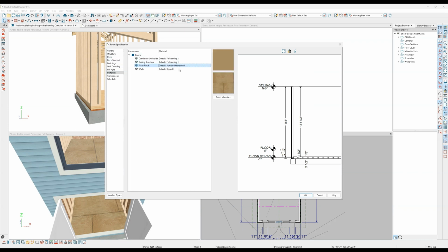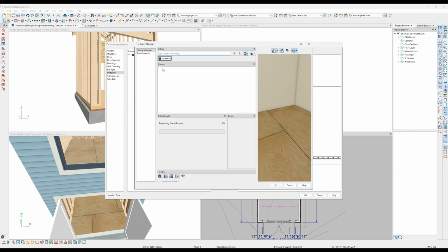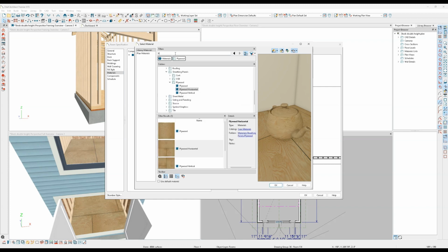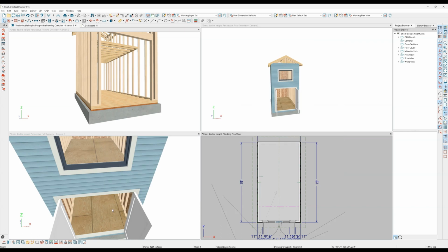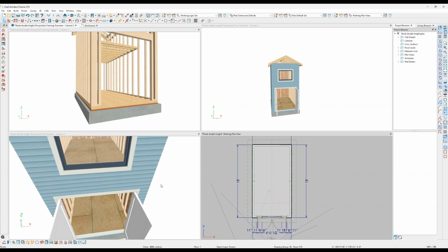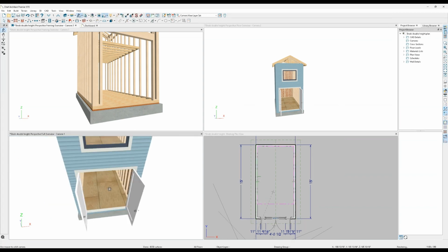And the same I'm going to do with the floor below. See, it's got horizontal as default. We're going to change that to vertical. And it should run it perpendicular to the floor joists. Remember, these are just 2x4s, nothing to it.